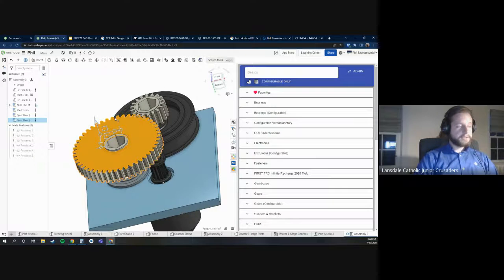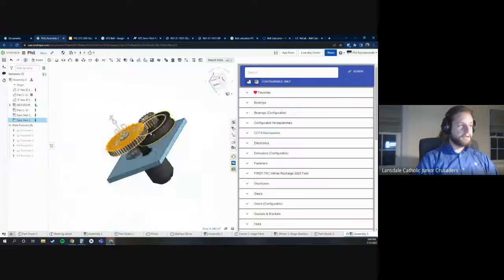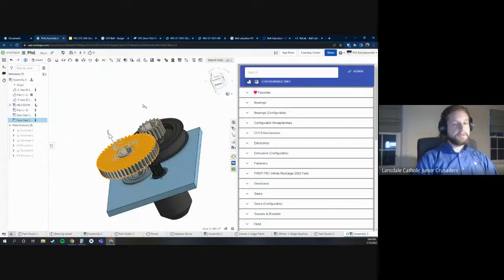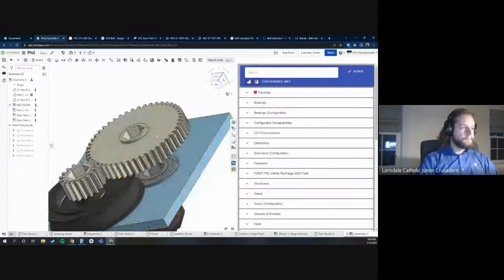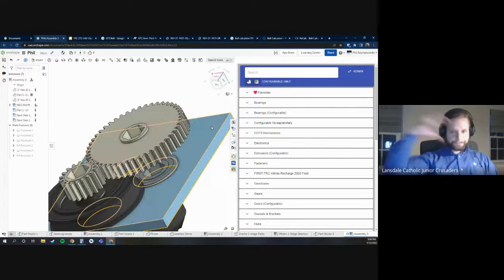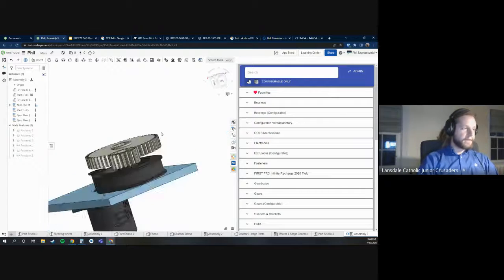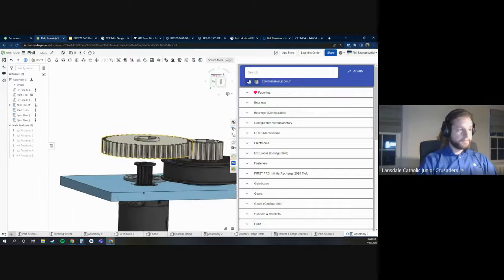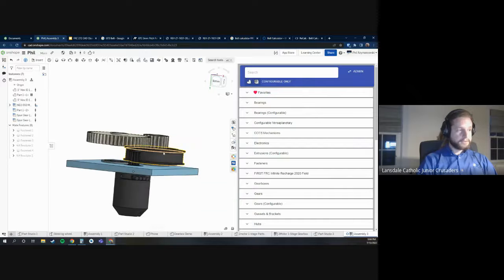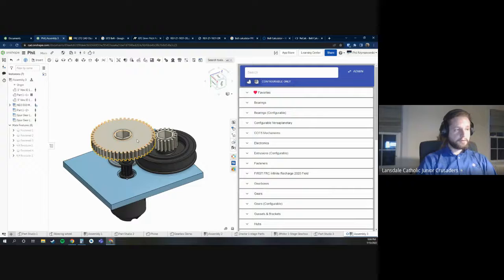And that's a pretty significant reduction in a very, very tight space. That is useful for things like when you need to lift heavy weights for your game, or when you need to rotate an arm that needs a lot of torque. This could be a good application for that. Or maybe when you need to lift the robot up off the ground, right? When you're trying to lift all 120 pounds of your robot, this could be a really good start of a gearbox for some kind of a winch.